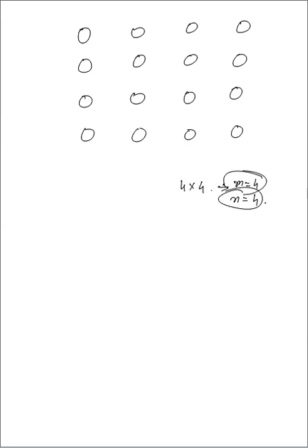D is the diameter of the pile and S is the spacing. Spacing means center to center. This is S. And this is half diameter and here also half diameter. So that will be extra, but the spacing will be S. So theta will be tan inverse D by S.